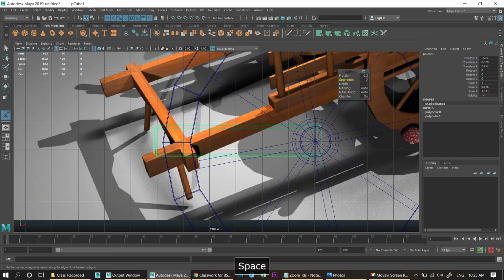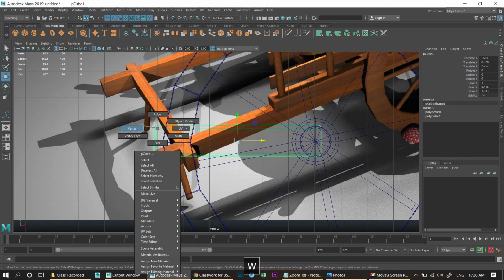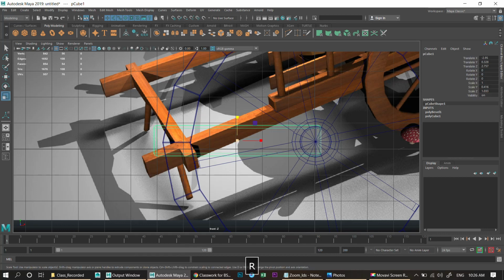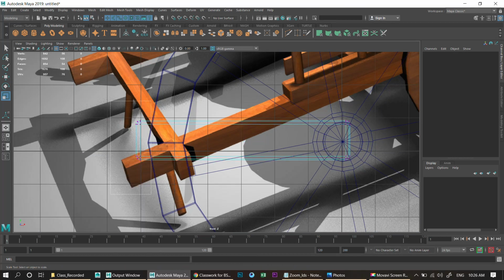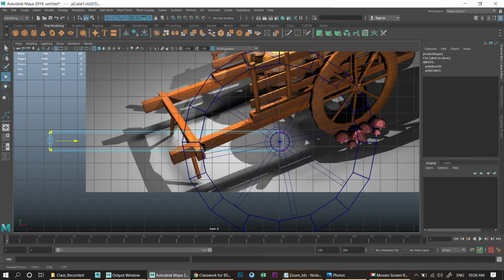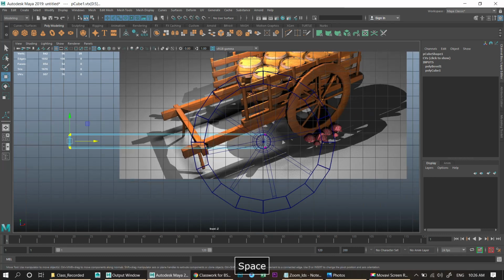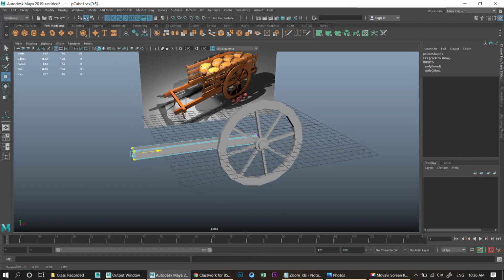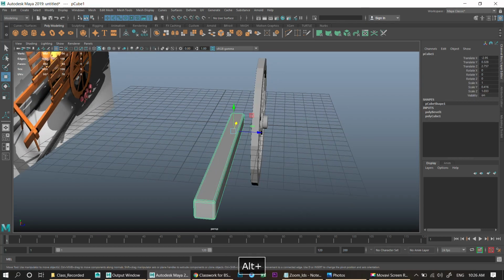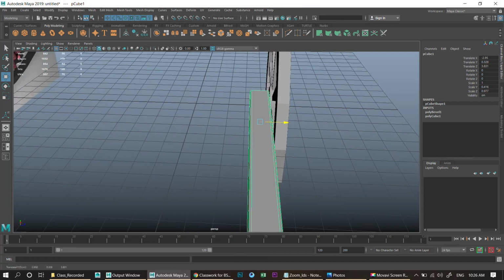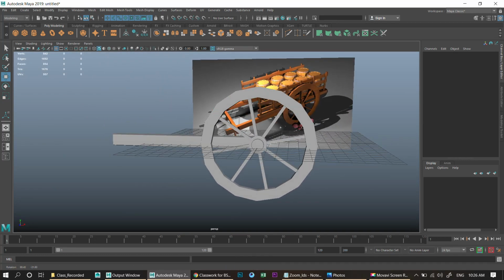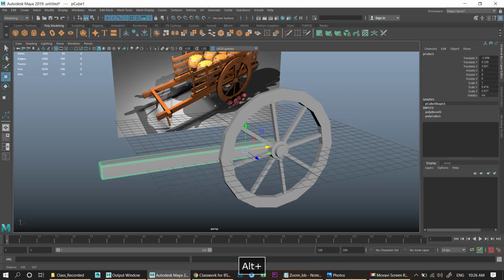If you forgot to increase the length, don't worry, but don't scale like this. Can you see the bevel edge distance getting increased? So right click, go to vertex mode, select this vertex and pull it to this distance. How much distance do you want? Yes, it's kind of balanced.